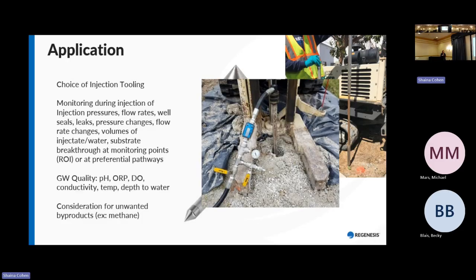In addition to that, making sure that during the injection itself, some really high level monitoring is occurring. On a really basic level, making sure that any of the wells in the surrounding area are just maintaining their integrity and you're not getting leaks from around them and things like that. But also looking at the flow rates and pressures that you're seeing at various injection points, and any sudden changes in particular in those flow rates or injection pressures can really be telling in terms of what's actually happening in the subsurface.